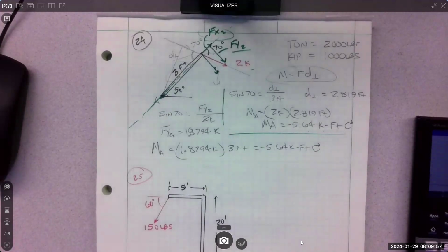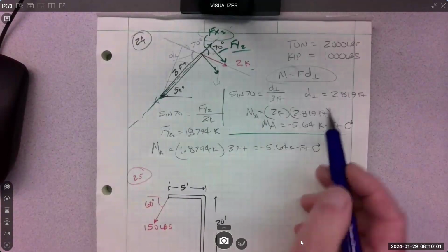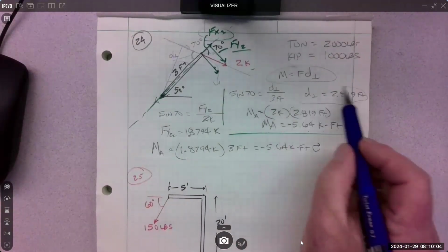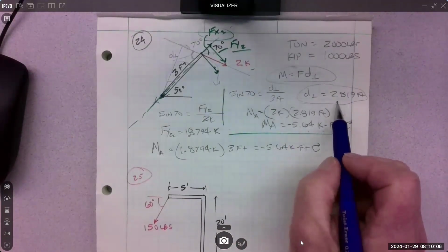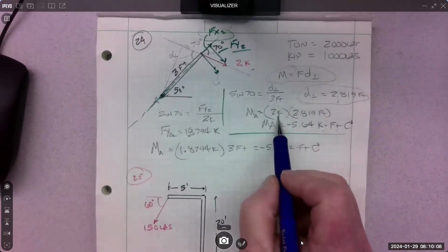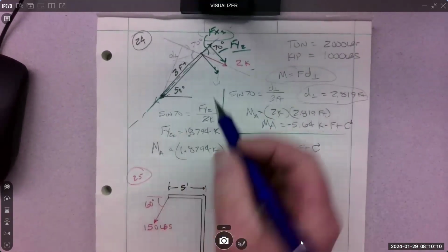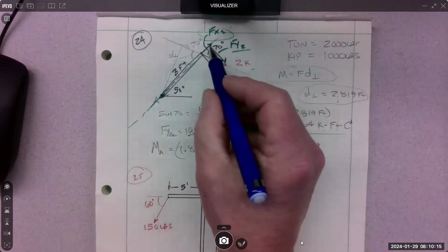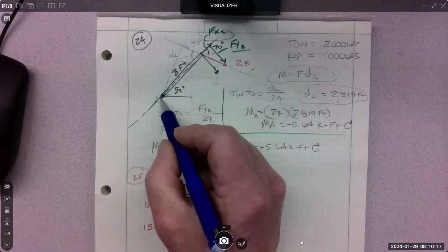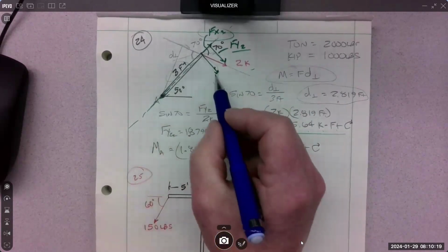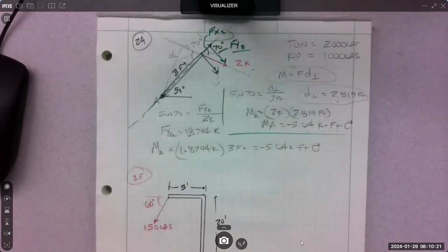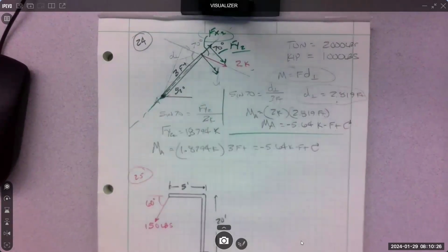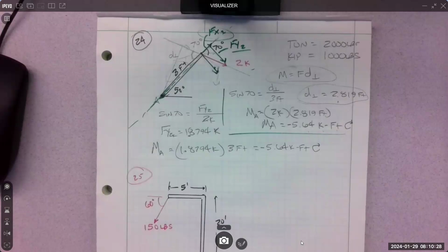So you can do components, or you can do the equation directly. The equation directly, just make sure you're using this perpendicular distance times the 2. If you're doing components, put the components in, think about which one drops out if one does. This one dropped out because it goes straight through the point. All the moment is created by this Y force. So 2 different ways, same solution.